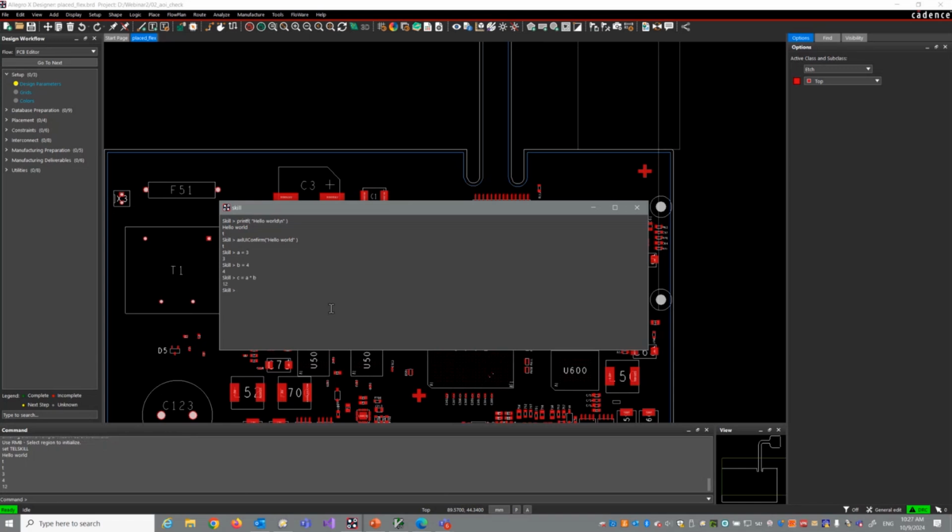So you can play with your commands. Now, how do I interact with the database? Say, for example, I would like to know how many nets we have. We can say netlist, I put it into a variable, nl equals axlDBGetDesign. This is really a very useful API. It gives you the root DB ID of the Allegro database, of the PCB editor database.